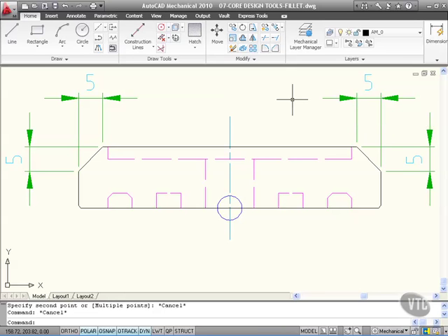Our next core design tool to look at is the Fillet core design tool. Very similar to chamfer, but what you're doing is instead of applying a distance, you're applying a radius. Now this curved groove here hasn't got a curve yet. It needs a curve on that corner, a radius. Now the distance from there to there needs to be measured. So let's measure that first.